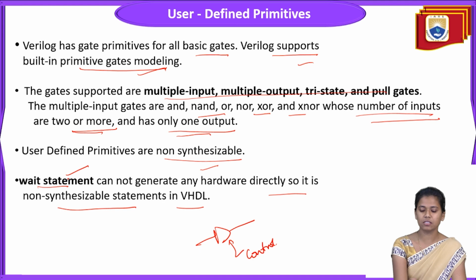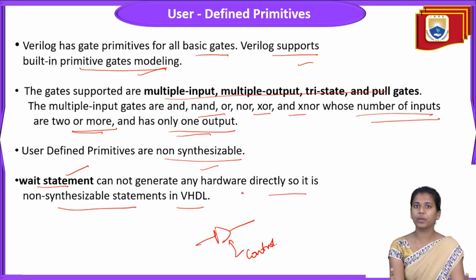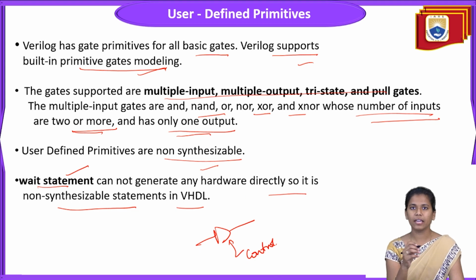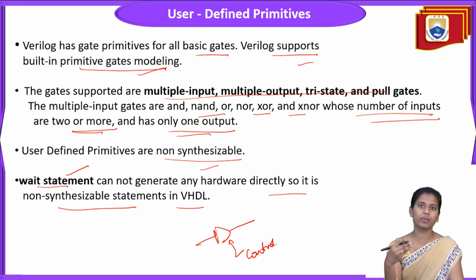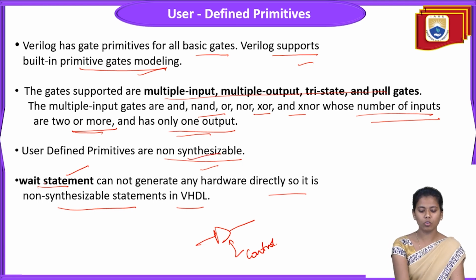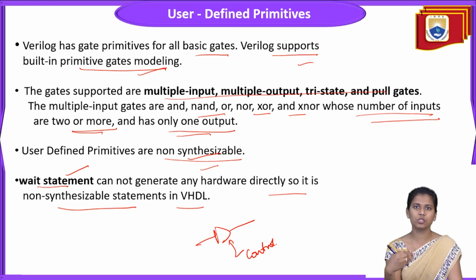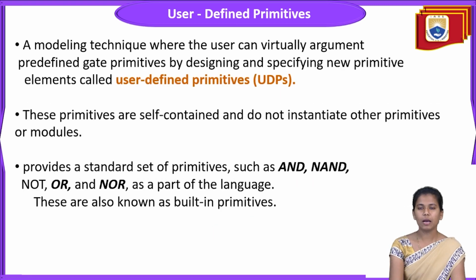This wait statement is non-synthesizable. That means we cannot generate any hardware directly, so we cannot directly introduce any hardware component in between. This is nothing but a non-synthesizable primitive. Not only the wait statement, we have a few more statements. In the further sections we will discuss what those non-synthesizable statements are, but in fact they are not important to be discussed.